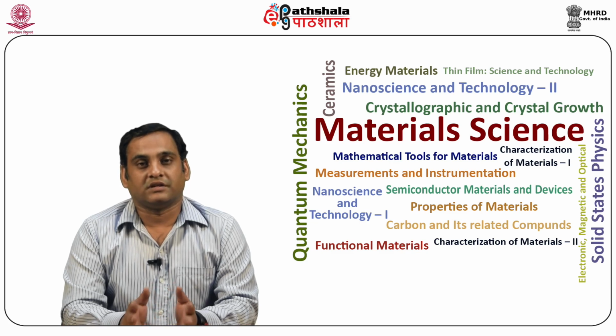Magnetostriction of single crystals. When an iron single crystal is magnetized to saturation in a [100] direction, the length of the crystal in the [100] direction is found to increase. From this, we infer that the unit cell of ferromagnetic iron is not exactly cubic but slightly tetragonal. A tetragonal cell has 3 axes at right angles, 2 are equal to each other and the third is longer or shorter than the other 2.